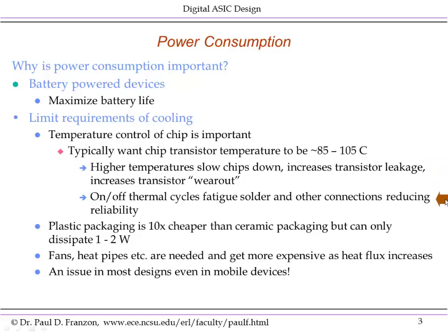But practically, the issue that makes you want to control the temperatures inside chips is the on-off thermal cycles. As you're most probably aware, different materials expand at different rates when you heat them up and cool them down. This leads to stresses at the joins between those materials. So as a chip is turned on and turned off, or goes to low power mode or high power mode, everything's expanding in and around it, and particularly the solder joints are being stressed in different ways in each different thermal cycle. This leads to fatigue, much like when you take a piece of metal and keep bending it over and over again, it will eventually break.